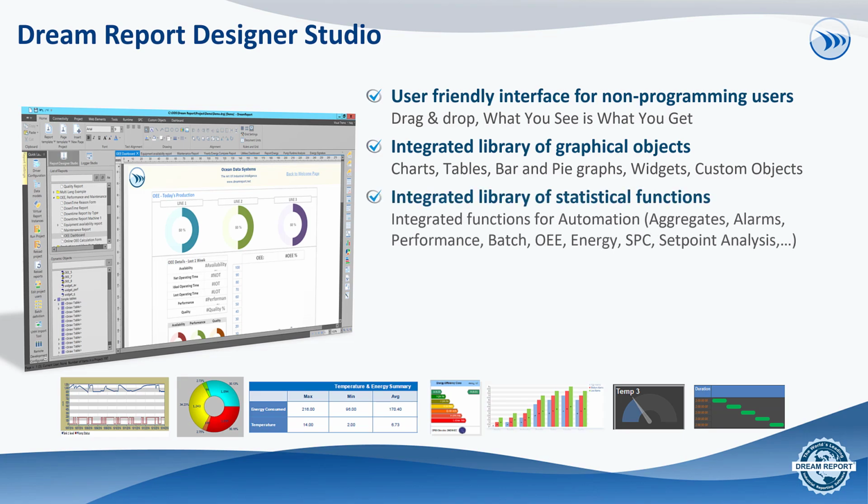As important, maybe even more important than these nice graphics, is this large library of statistical functions or KPIs, metrics, whatever you want to call them, that are all built around and optimized for industrial and process automation reporting. So things like equipment up and downtime and utilization, alarm analytics: show me the number of nuisance alarms, give me the highest rate of alarms and when did it occur. These are all calculations that are ready to go, that you point to your raw data and then put into a context that's now useful and usable to somebody who's viewing those reports or dashboards.